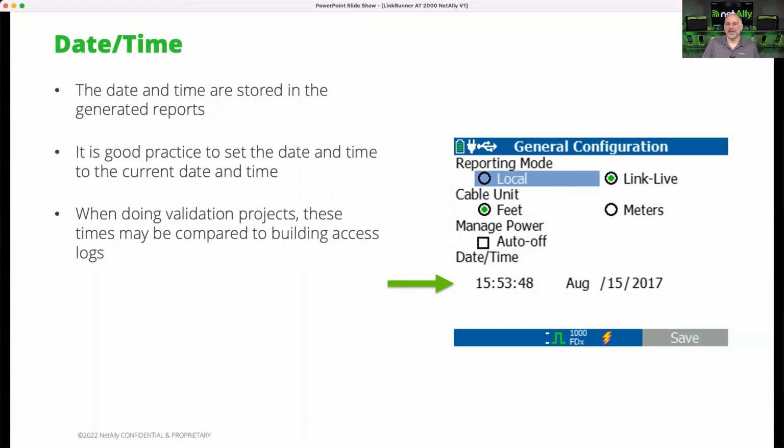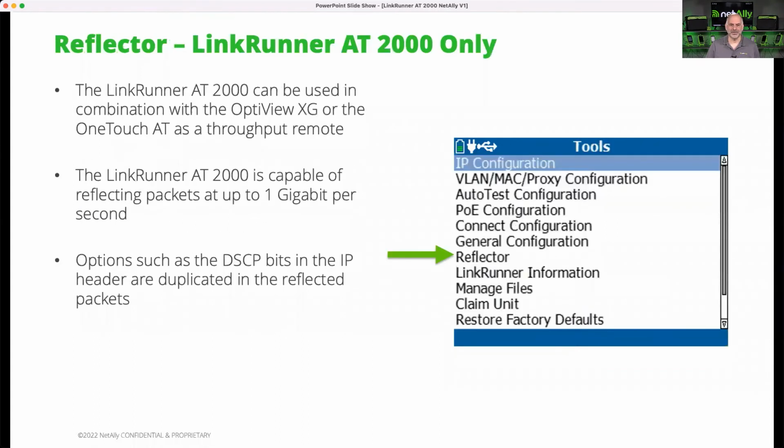I always like to check my date and time before I go out and start doing my testing so that it's correct in all my test results, because that's going to be burned into that test result. So before you go out and start working with this, it's a good idea to check the date and time, and make sure those are correct so that you're not putting the wrong date and time into your test results.